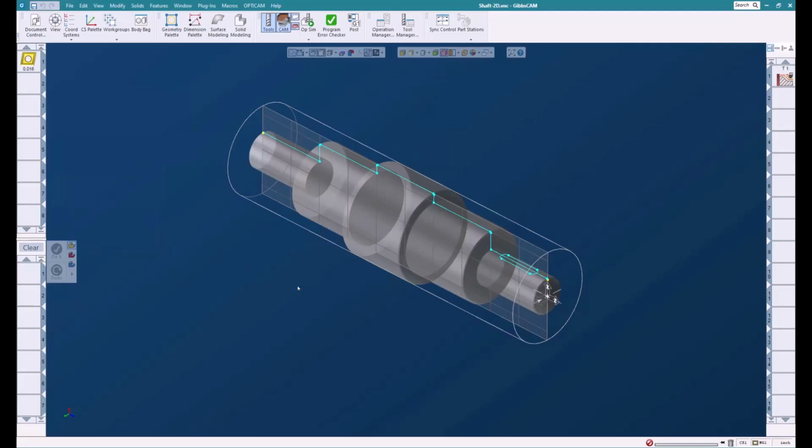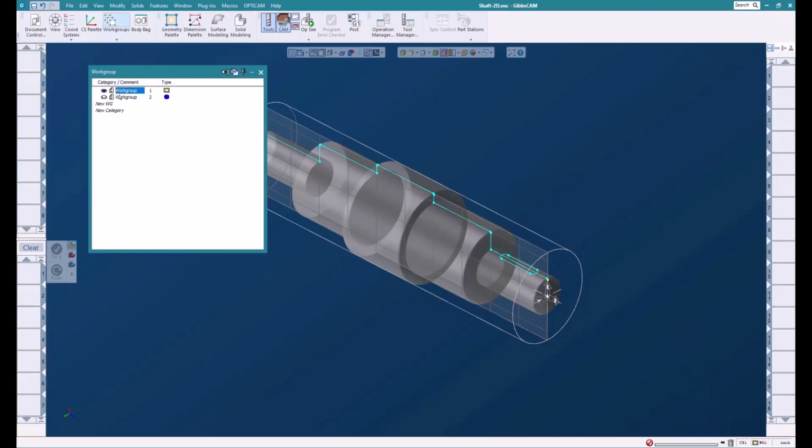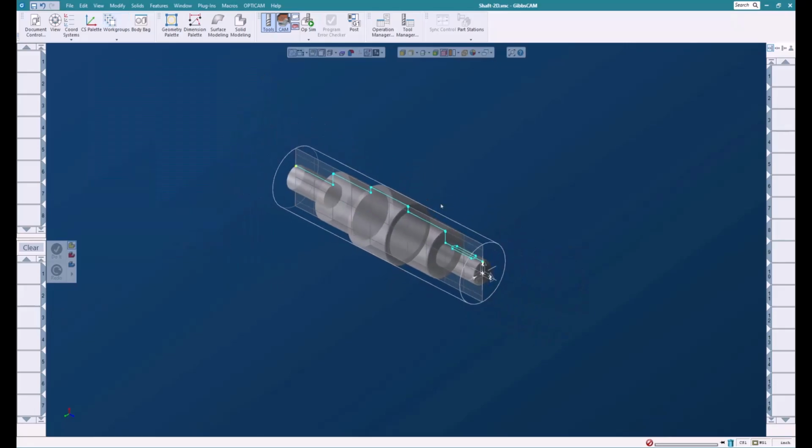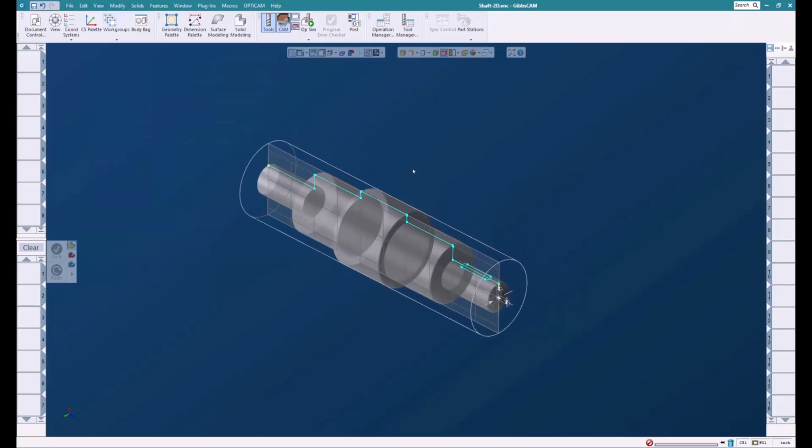Now that we've saved it, we need to get rid of all the lathe bits that we don't need. Okay, like the tool paths and the tools. So let's do that. So we're going to throw the tool path away. We'll throw the tool away. And I'm going to go up and get rid of the work group that I used to generate the initial stock for this part. Okay. And I just used a revolved geometry.